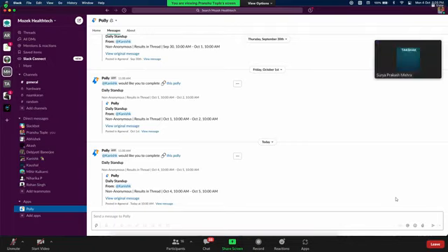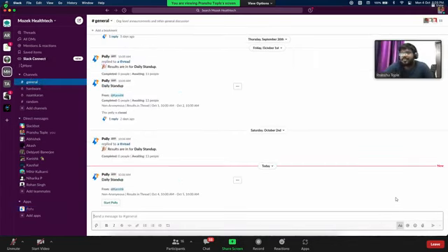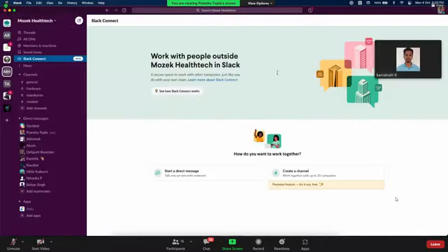Hello, is my voice audible now? Yes, you are audible. I am launching gazebo.launch first and movebase.launch second, like a navigation.launch file. After that, I am teleporting my robot somewhere in my house to a certain distance. After it's moving there, I close all the nodes and restart them. Whenever I restart, the robot is not in my home position. It needs to come to my home position automatically whenever the nodes are restarted. How can I do that?